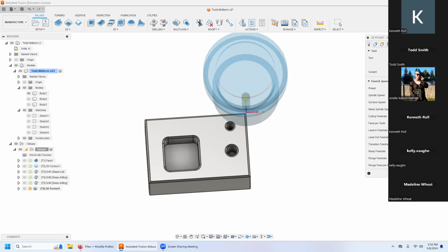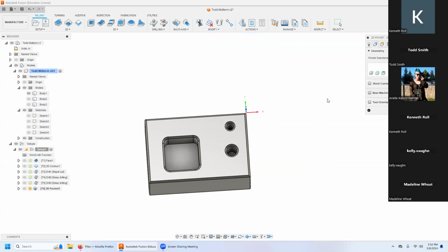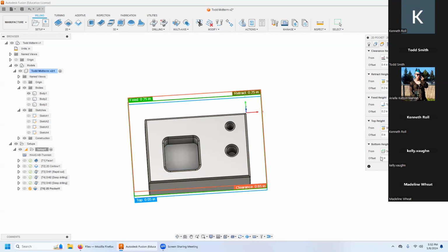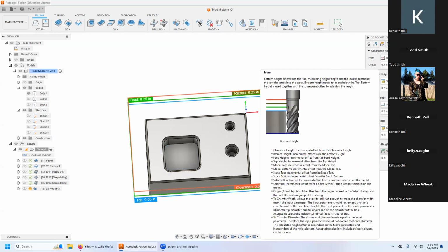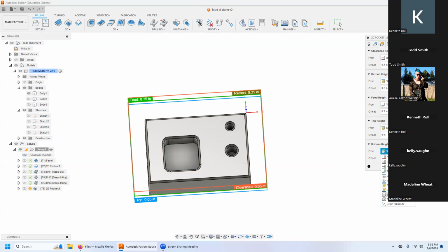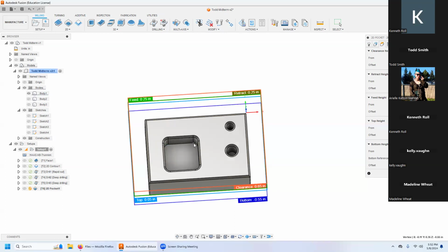Okay, plunge. They've got that down to 20 already for us, so we'll take it. The pocket. You can choose what you like here to make it work. I tend to like chain, personally. It's what I trained on most. Okay, there we are. We'll make sure the arrow is on the correct side of the line. I think everything is good there. Our heights. We could use selected contour. I'm going to go with selection, though. It's up to you.